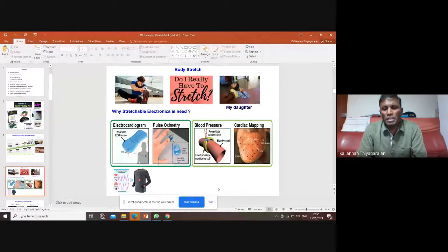In 2D materials, graphene is widely used, based on the approach. Actually, it is not intrinsically stretchable. The intrinsic stretchability of graphene is only 5.3 to 5.6%, so we cannot really use it directly for applications. We need at least 10 to 15% stretchability even for small devices. So people use graphene with a buckling structure more. For transistors they used it,